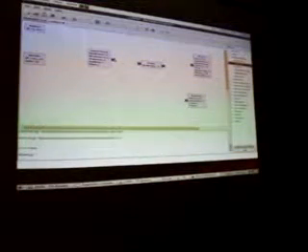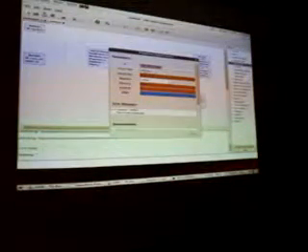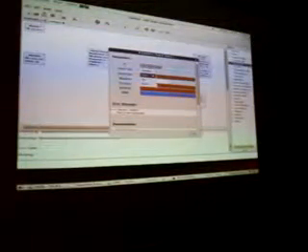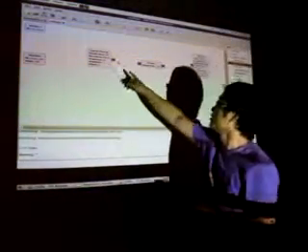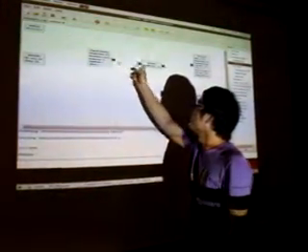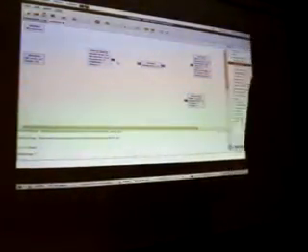Since GNU Radio requires that the output of a block and the input of the next block must be matched, we can see the output type here. The blue means the output type is complex, and if we change it, the color will change. So it's very convenient to view that. Here I changed the output, so the color changed. Different colors cannot be connected, and if you connect them, it will be an error.